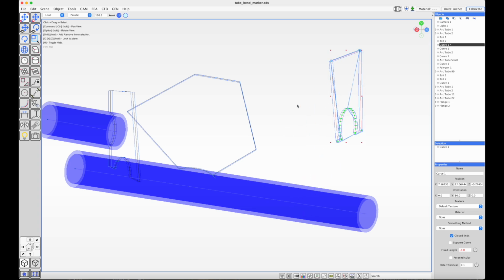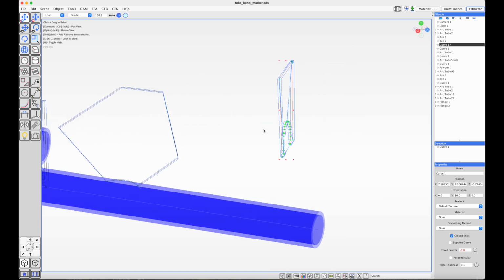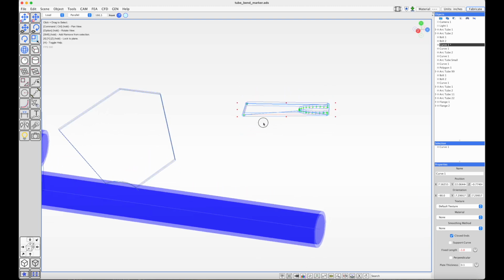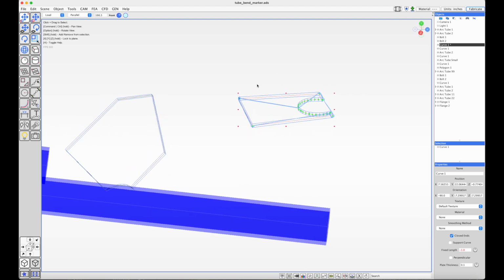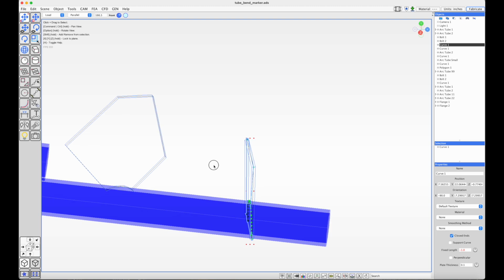So I can move it and align it with other parts and use this flatten tool. And this will align the part on a flat surface so that I can pack it along with other parts and then generate G code with this on a flat table. So the plasma table is always going to cut parts laid flat. So this is in the layout mode. So when we're done, I can go back to modeling and it will be rendered in the 3D space.